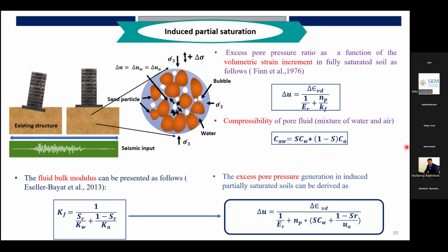So this has been theoretically expressed, and finally we are bringing in the degree of saturation. The excess pore pressure generation we can estimate using the volumetric strain with the help of the bulk modulus, or fluid bulk modulus. So that is what we are bringing into a theoretical formulation.